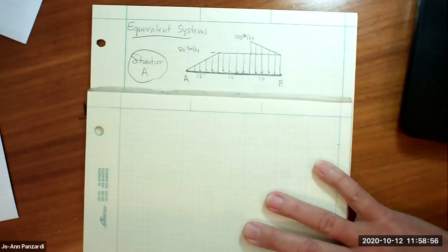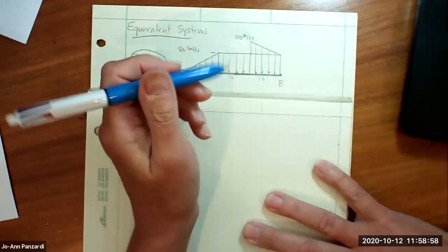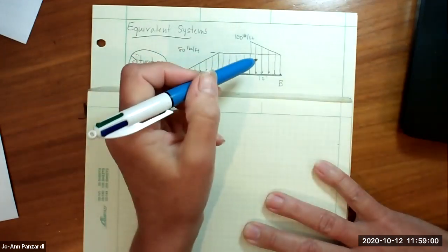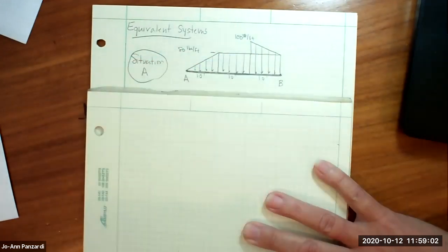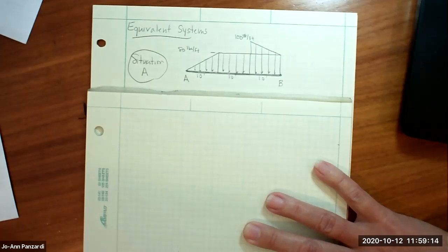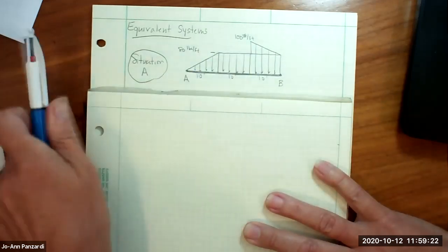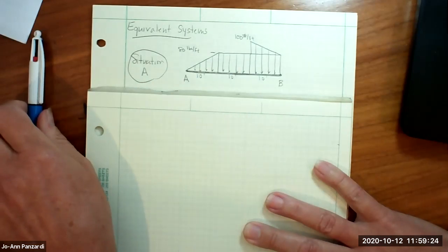Now, we could deem this a trapezoid, but then we would really have to know what the centroid of a trapezoid is. Certainly we could find it by integration, or look it up on a chart. But rather than doing that, I prefer to just remember the centroids of triangles and rectangles. So I would divide this up into 4 sections.